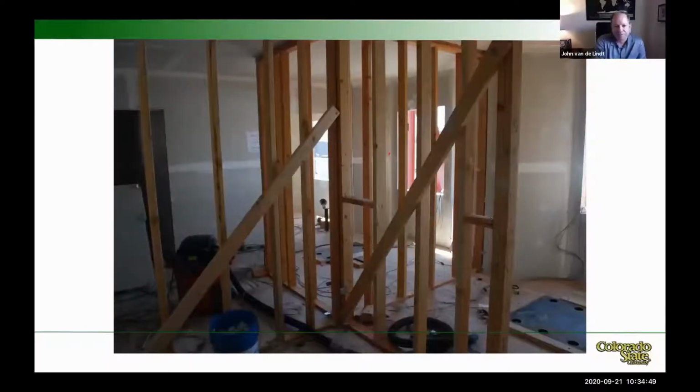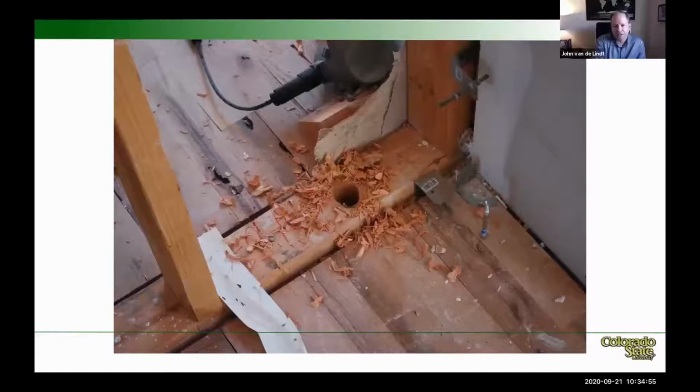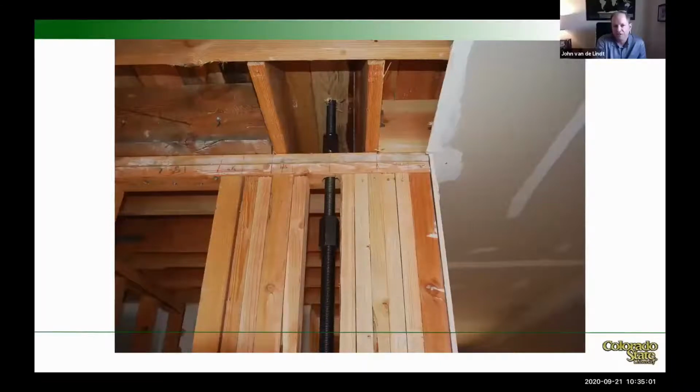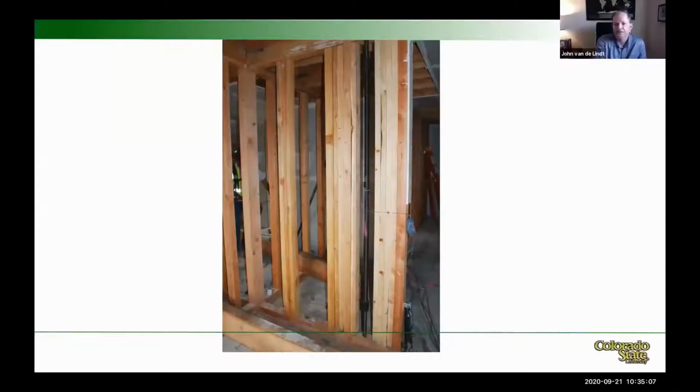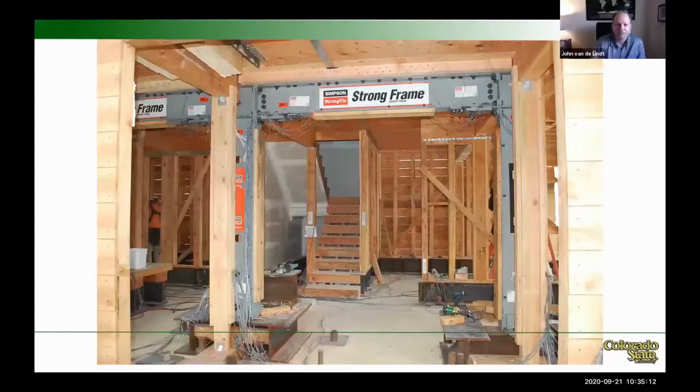So this was the big center of the building, intersecting shear walls and putting in continuous ATS rods. And here you see going through the floor. So we're pulling drywall out, working on this, a big stud pack being toe-nailed in. And here you see on the bottom floor, so remember this is a 2-bay frame in the direction of the motion, and then right above here you can see the shear transfer from the frame into the diaphragm, and then above that is the stack of shear walls, that intersecting shear wall. And so just a quick video.